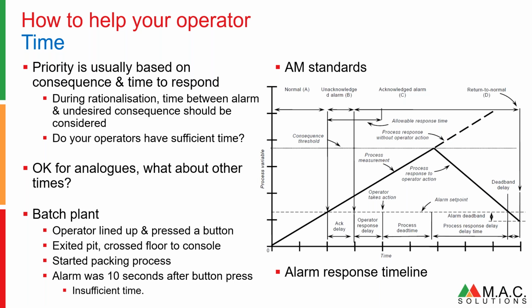But after pressing the button, the alarm was enabled after 10 seconds. It didn't give the guys time to get across the floor, which should have been 30 or 40 seconds, and the transfer did not start until the guy pressed the button on the graphic. So this alarm occurred every time. How difficult a job was that to deal with, to change that time from 10 seconds to 30 or even 60 seconds to give the guy plenty of time, and then you start monitoring the flow. Not difficult.